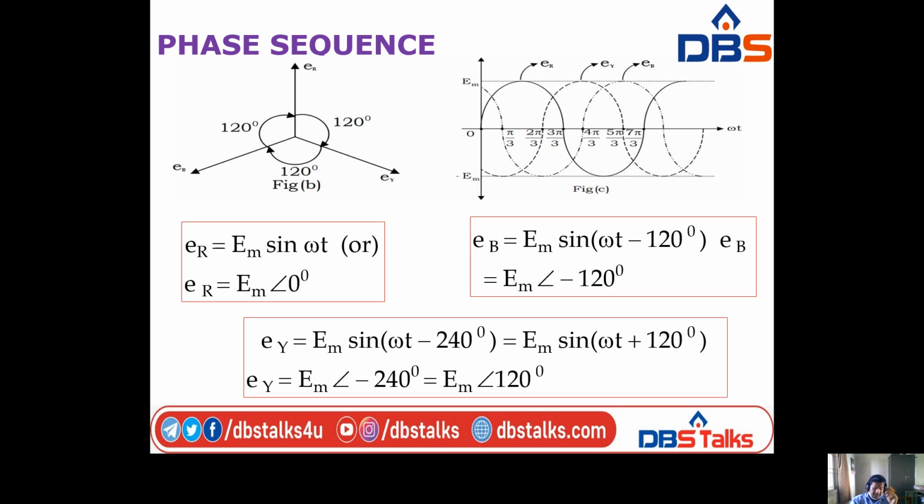Mainly the phase sequence depends upon the direction of rotation of the coils in the magnetic field. That means if the coils rotate in the opposite direction, then the phase voltages attain maximum values in the order ACB. Suppose in anti-clockwise direction, this is RBY. Suppose clockwise direction, RYB. The phase sequence gets reversed with the direction of rotation. Then the voltage for this sequence can be represented as,